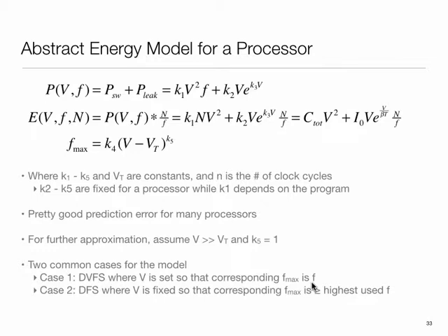There are a couple of ways of doing it. You calibrate the system, create a table so that you have a voltage-frequency mapping, and then you take into account the temperature and so on. Alternatively, there are circuit ways of doing it. You could design a frequency generator which automatically sets the frequency such that it matches a certain delay. Okay, so you can design circuits like that.